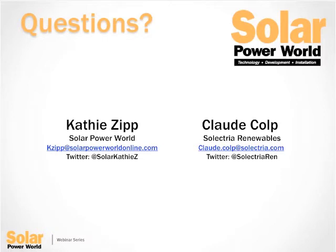Thank you. Kind of keeping with arc faults, someone's wondering, what happens if the arc fault is in the PV output circuit rather than the PV source circuit? Is that possible? It is possible. It's less likely, but it is possible.